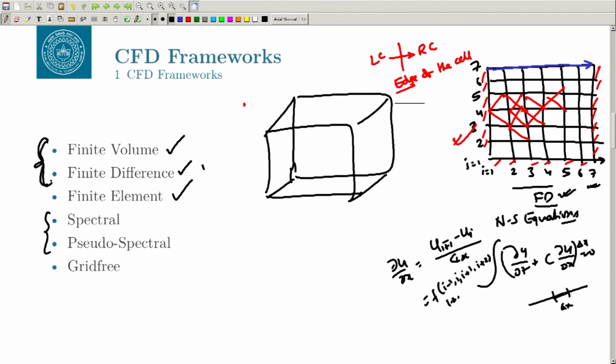box, okay, and you put some disturbance in the beginning, okay, it may be your sinusoidal vortex or anything that you want, and then you put in the Navier-Stokes equation. Because of the non-linearity, the turbulence will develop and you will get more and more structures in the flow, and you might want to analyze what happens when you change the Reynolds number, what happens when you change the grid size and so on and so forth. So, if you just want to analyze this, you do not need to have a boundary layer, there is no wall, nothing. Okay. So, in this case you can utilize for example, a periodic boundary condition. So, whatever is getting in is getting out here, here, and then this side and this side, right. So, in this case you can utilize your periodic boundary condition. So, whenever there is a periodic boundary condition, you can use the spectral properties, right.